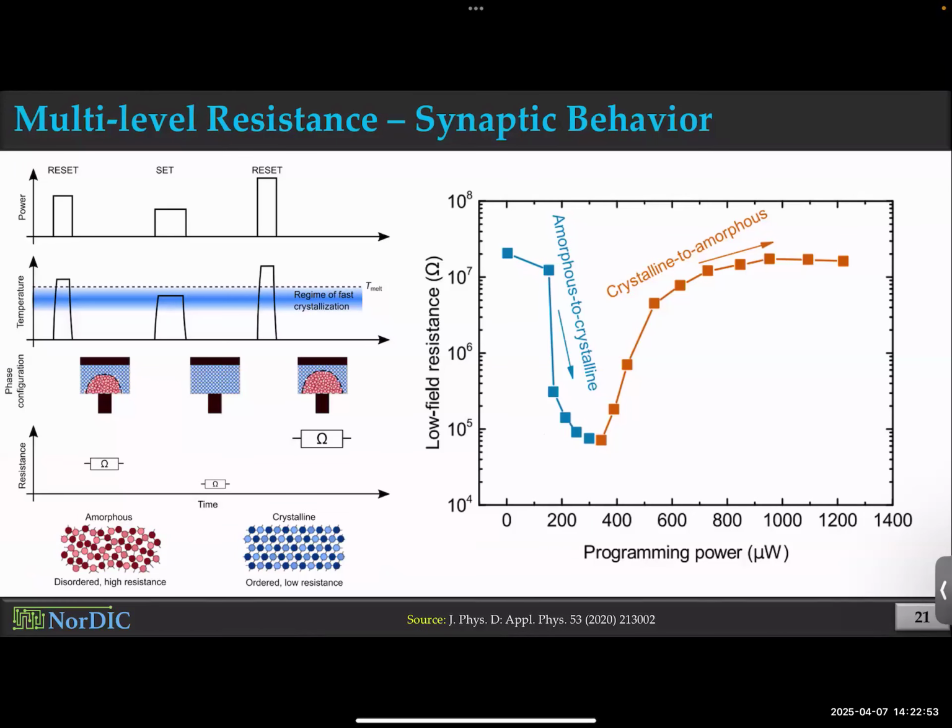Okay, then this is new. This is definitely new. So we will spend time to discuss this properly, all right? So multi-level resistance. Good thing is by now you hopefully know the use case for multiple levels in a memory cell. If you have 4 different resistance levels, you could use them to represent, remember, 00, 01, 10, 11. 2 bits at a time instead of 1 bit at a time.